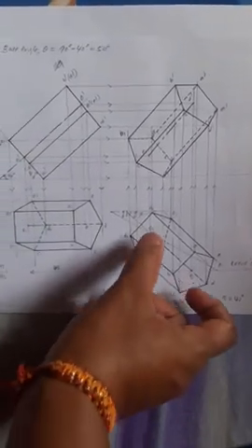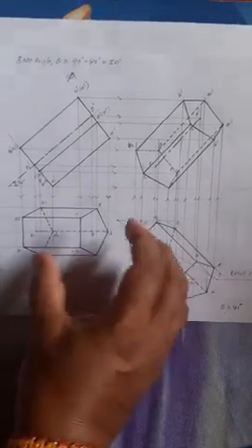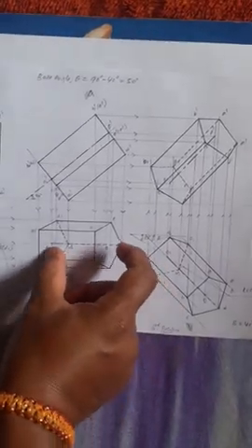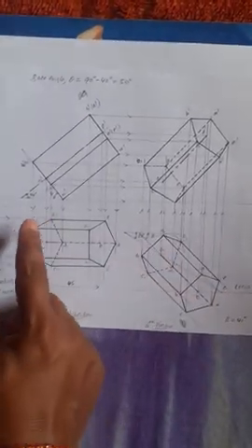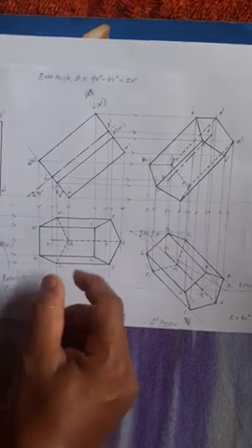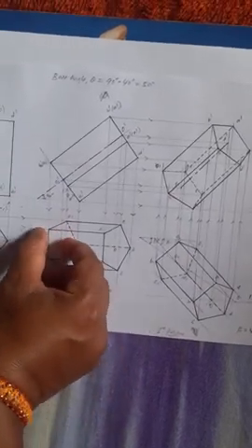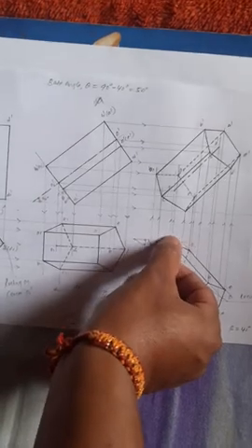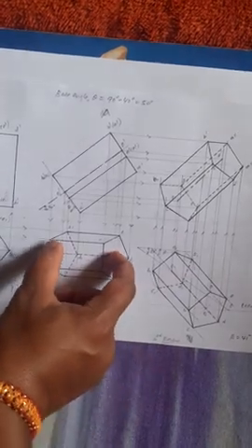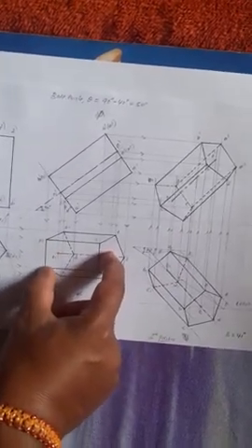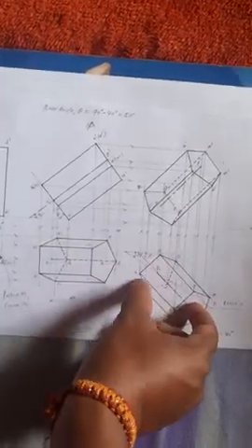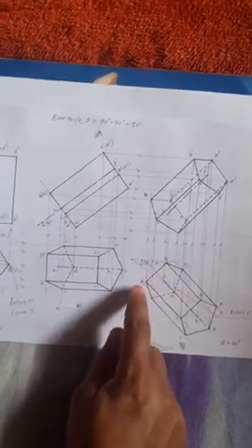Now on the O1 O, this axis beta degree line, we place this solid. First you place O1 O. Once you place O1 O, now the bottom face, the base corners are there; just transfer them here. How do you transfer? As you know O1 A, we know the radius. Draw an arc O1 A, that is equal to O1 B, draw an arc. O already we know, O to A1, O to B1, the radius is the same. Then draw arcs from O as the center, O1 A and O1 B. Now we get the corners A1 and B1.